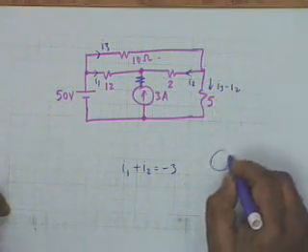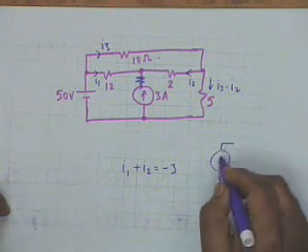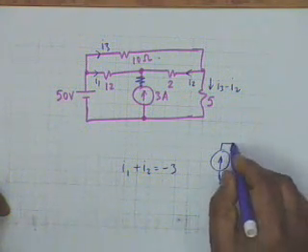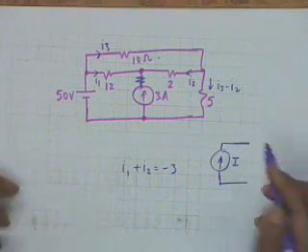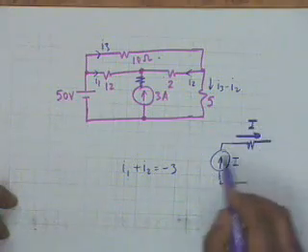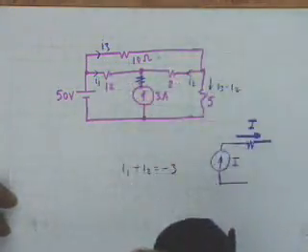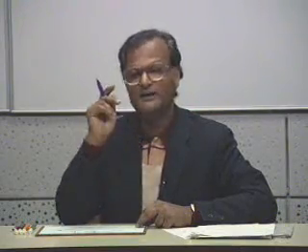No. A current generator by definition delivers a current capital I irrespective of what is connected to it. If there is a series resistance, it does not matter. The current is still I, whatever the resistance, except in a degenerate case: if capital R is infinite, then the current generator is disconnected and therefore no current can flow.